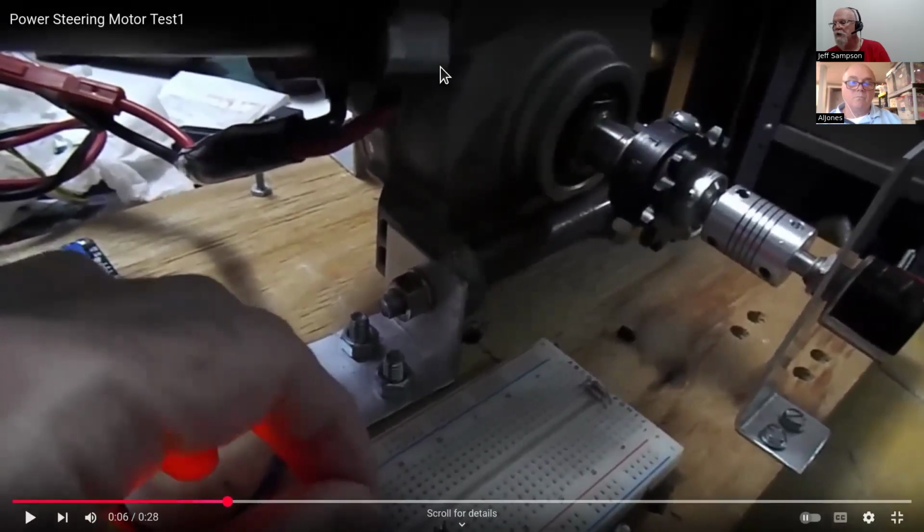So a couple things to notice. This is the power steering motor here, and here's the actual motor, and this is the gearbox with the shaft sticking out. And I just have a 10-turn potentiometer on the end of that to measure its position. And then down here on this board, I've got an Arduino Nano and a potentiometer to request the position for it. And then back here is that 30 amp, this is a different Cytron board. This is a 30 amp version of that board I just showed you. And I've got some code in here that says, read this potentiometer, and then turn it with my fingers, and then turn the motor to match that.